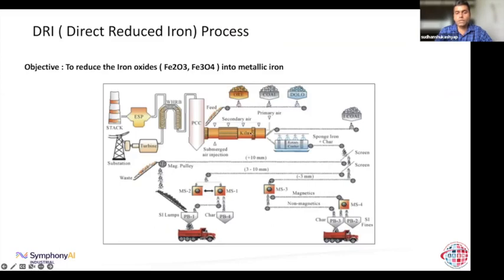You could see here a kiln in this process flow diagram, and this is a rotating, high temperature, long reactor, which is being used to do this reduction of oxides to metallic iron. So the feed to this kiln reactor is iron ore pellets. These ores, oxides, are pelletized up front and fed from the front end of the kiln.